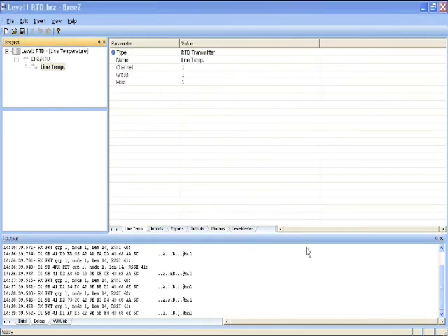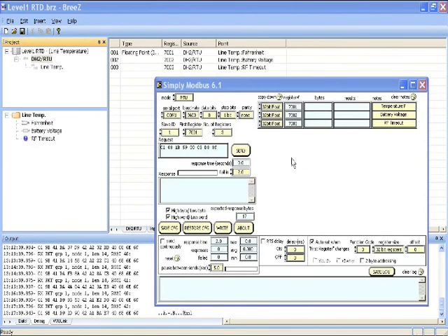Now that we know that our Modbus data is being reported to the DH2 on 1 minute intervals, we can move forward to set up our Modbus master. Today we will be using Simply Modbus. I set up my Modbus master across COM1, 9600, 8, none, and 1, slave ID of 1, my first register of 7001 for 3 registers.